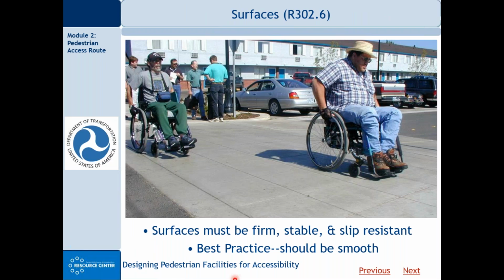And remember, the obligation is make it accessible to the maximum extent practicable, and then document a technical infeasibility. Show what options you looked at, show how it's accessible to automobiles or vehicles, and also how you tried to make it accessible for pedestrians, especially pedestrians with mobility assistive devices.